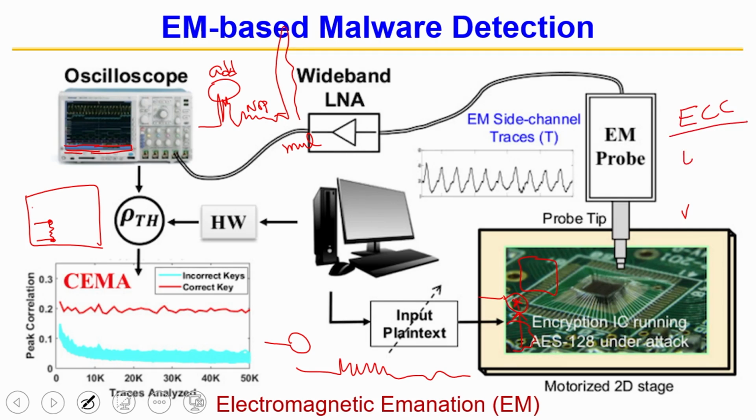It has a silly computation inside. If the ith bit of the key is 1, then do something, else do something. This loop has more instructions than this loop. If somebody is observing power variation and you see it goes up, then little, then it goes up and then little, then you know this one is 1, this one is 0, this one is 1, this one is 1, this is 0. You can exactly figure out what the key is.